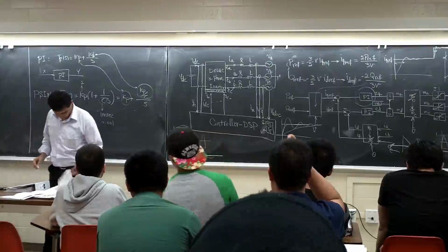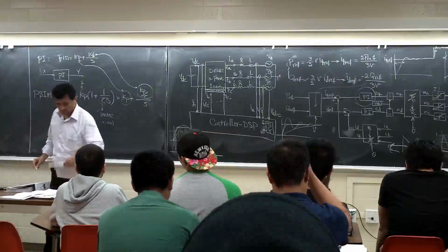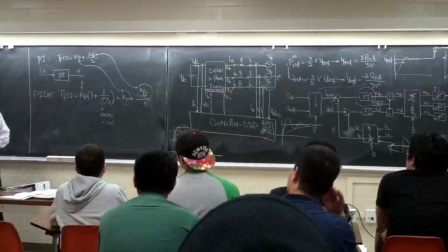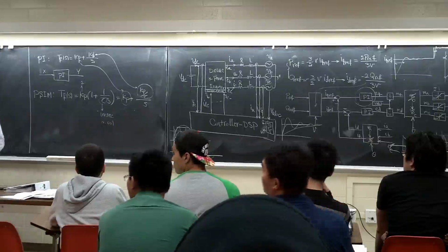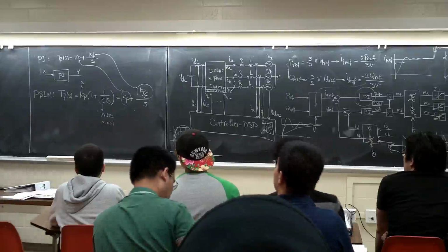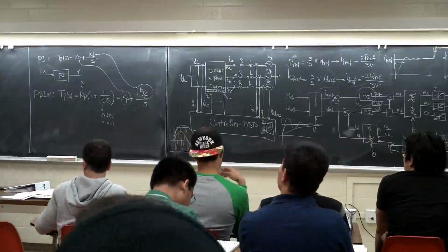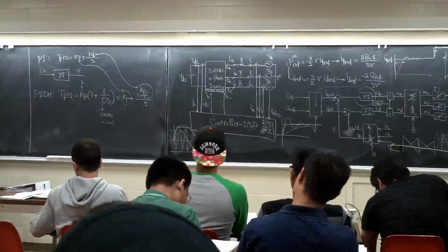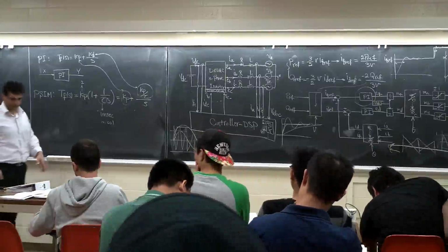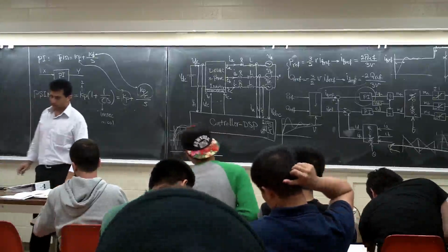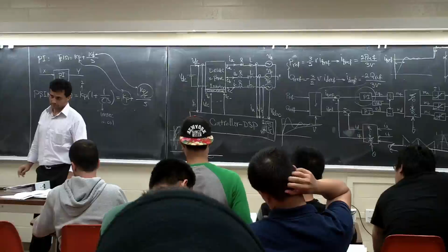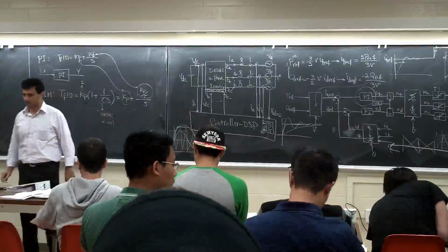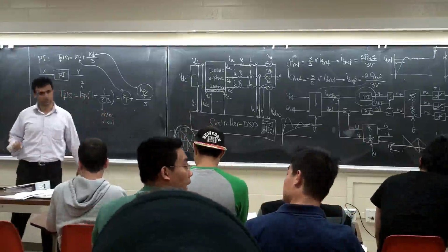So we finished this part. Now, any question here? We are going to get heavily involved with the math now. Any question? Is that a range of the Kp? Is that a maximum range? No, you have to use a design. This is design. You design the system. We'll get to the design part. I thought I was going to finish that one, but no, I'm not going to get there. But I'll tell you how you get a transfer function for the system. After that, you can do the root locus or a Bode plot or something like that to select these Kp, Ki values. You plot those and you see where you are.